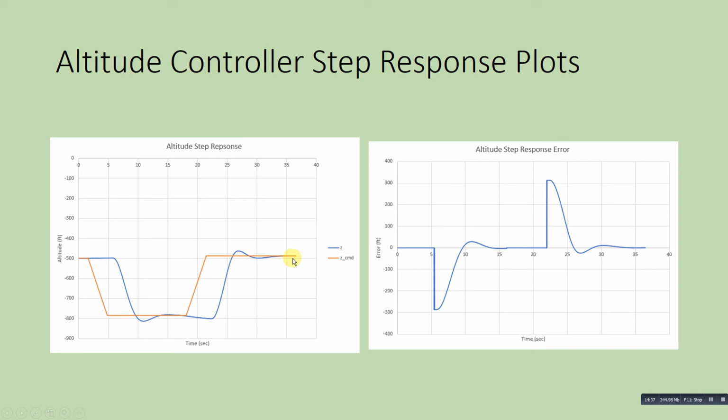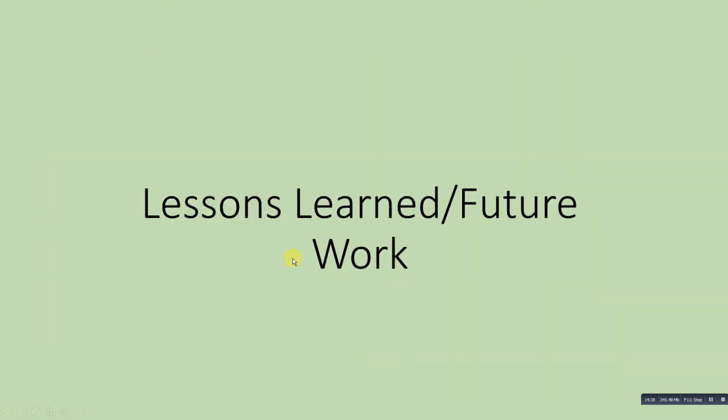Now I just wanted to conclude, basically some lessons learned. As I went through this, I was able to understand that proportional controllers actually do work fairly well. Although they won't ever drive the error in your system to 0, they do work. And also using that 3 cascaded loop system.